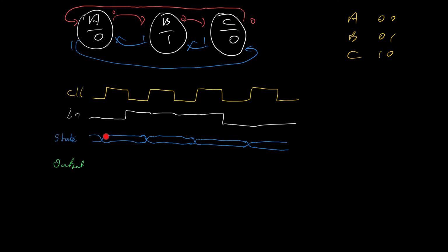Internal to our finite state machine is the state, which is represented by the outputs of the flip-flops. Now in this particular case, we know that the state, because I've given the state representation, is 2 bits, and I could in principle have drawn 2 different lines here, one to represent bit 0 of the state and another wire here to represent bit 1 of the state. However, I will use the compact notation that ModelSim uses, and this denotes that I have multiple wires here, and I'm going to just draw in the numerical value of the state. So I can draw in 0, 0, 0, 1 or 1, 0 into these to indicate the current state.